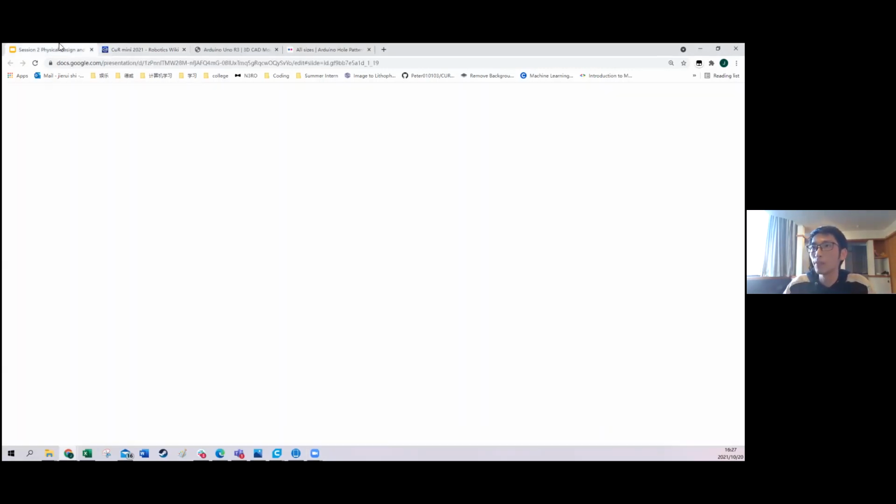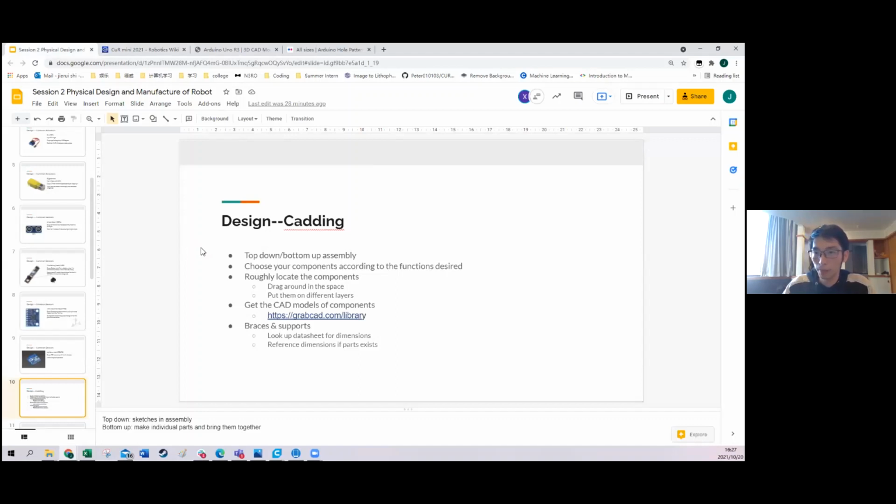parts for mounting. Whenever you are designing something that's symmetric, it will be really useful if you use the mirror feature in the CAD model, because, for example, it's almost entirely symmetric, and if you are doing the dimensions from left to right, say this is 200 millimeters, this is 10, and you make this 100 and this distance 190, from this side to this side, it would be really hard when you try to adjust the width.